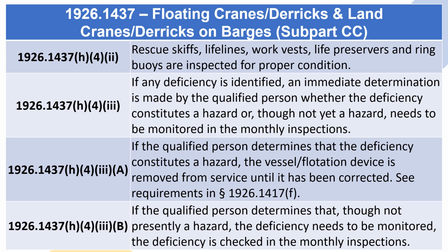1926.1437 H4-3 A and B. If the qualified person determines that the deficiency constitutes a hazard, the vessel/flotation device is removed from service until it has been corrected. See requirements in section 1926.1417 F. If the qualified person determines that, though not presently a hazard, the deficiency needs to be monitored, the deficiency is checked in the monthly inspections.